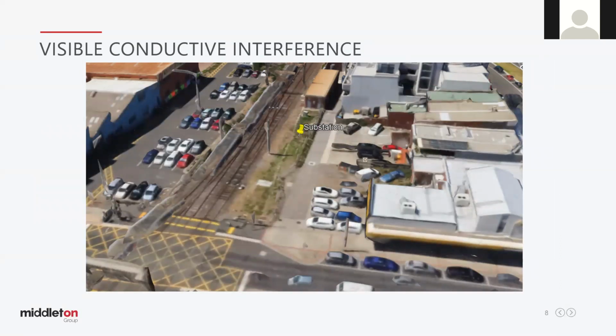Very difficult. We've got a lot of visible conductive infrastructure there. Might be a little hard to see, but we've got a metal fence down the side here that's in contact with the ground. If we're going to measure soil resistivity in here, the distance between the stakes effectively grabs a hemisphere of soil. The further you get out, the bigger the hemisphere of soil that you're measuring. And this steel structure, the fence, and indeed the concrete with the reinforcing in it, if it's going to have influence on that hemisphere, it's going to interrupt your results. They're going to be lower than the actual soil is.